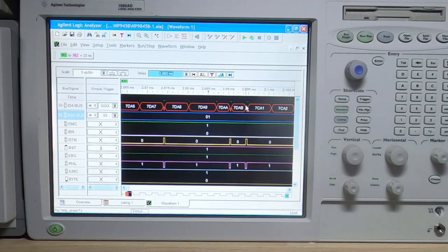It's going through a particular part of the buffer, resetting, going through the same part of the buffer again, and it's doing that over and over again, but it shouldn't be. This should not be reloading at this point, and the fact it's reloading means there is something wrong going on within the control board. And as I say, it's most likely because it's receiving a reset command or reload command.